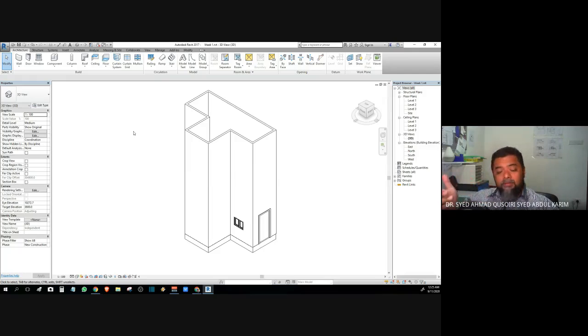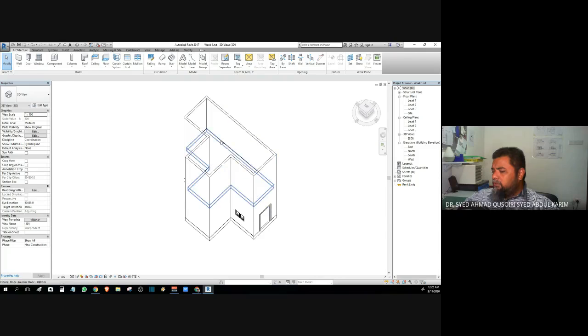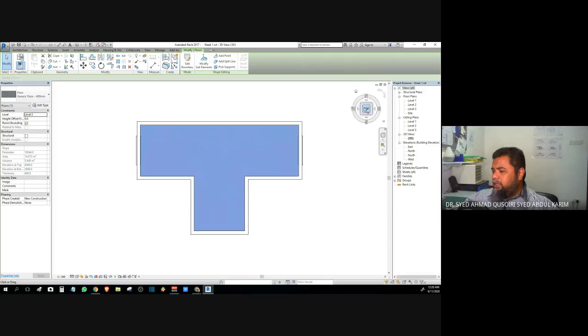So in this case, we've already put in a half brick wall, and these three faces of the wall. So we plan to change it to curtain wall. Okay. So normally what we can see here is that there is this upper floor, which is in contact with the wall itself. So usually what I would do is I would pull this upper floor away from meeting the interior face of the walls that I intend to change as a curtain wall.